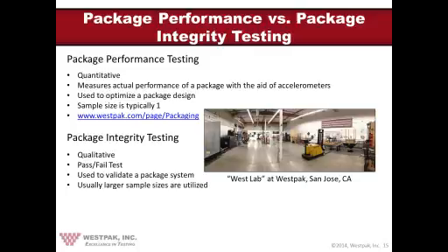Now, this is opposed to an integrity test. With an integrity test, envision some big scooper hands that go out and scoop up this distribution environment that Paul talked about earlier. They bring it into the laboratory, jack up the level in order to reduce the time, and subject the product package system to that. And then the end result is you simply open it up and make sure the product is in good shape. Good shape, what does that mean? Well, generally speaking, we like to call that the kind of condition in which you would want the customer to see the product.